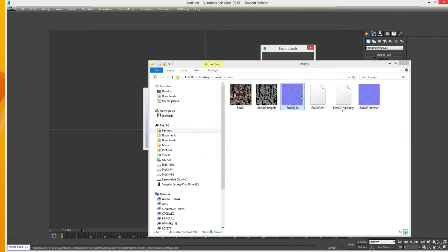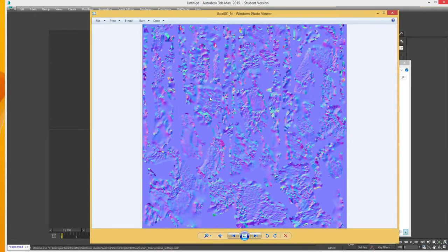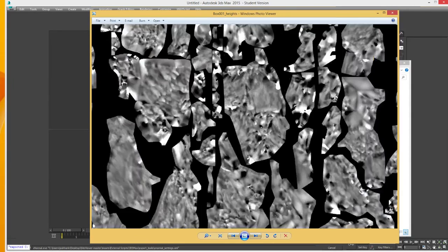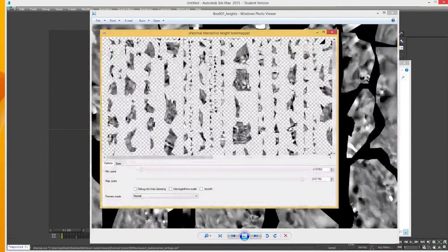This is the normal map, which is giving information about which direction parts of the face are aiming so that light will respond in different ways on it. And then the height map is actually pulling and pushing parts of that surface to recreate the detail of the original model. So it's recreating the geometry of the high poly model onto the low poly model using a very different technique, doing it in a very different place.